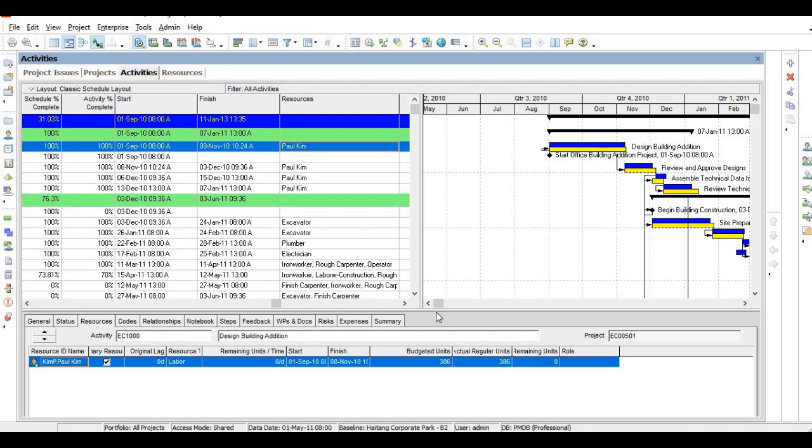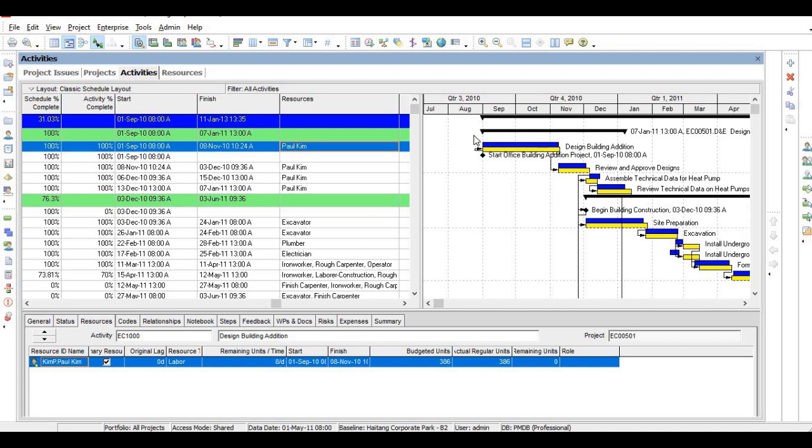So how is the tracking of progress done? You have to save the baseline. Baseline is nothing but your original schedule. Your original or approved schedule is taken as a copy. That is called the baseline. Based on the baseline, you have to take the actual progress. This blue color line will show the progress. Normally your project manager will ask for weekly, bi-monthly, or monthly reports. Based on that, you have to set a status date. Status date is nothing but the date by which they want to see the progress.